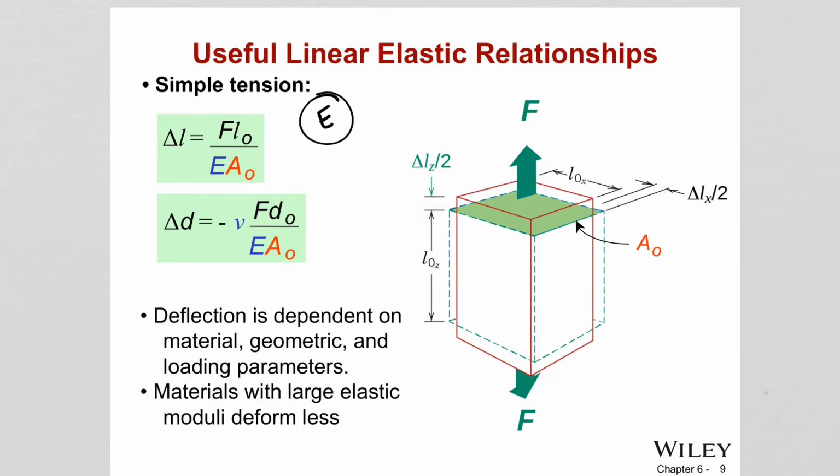Okay, so this Young's modulus or elastic modulus is a property of a material, and basically comes from the atomic bond strength. So if a material resists elastic deformation, it means it has a large elastic modulus or Young's modulus. It means the atomic bonding is strong, and we saw that parameter when we were looking at atomic bonding.